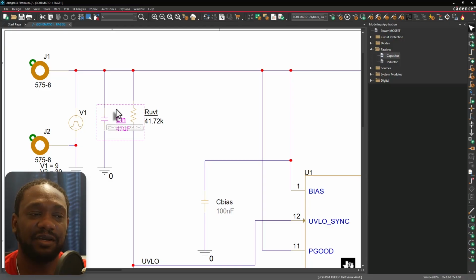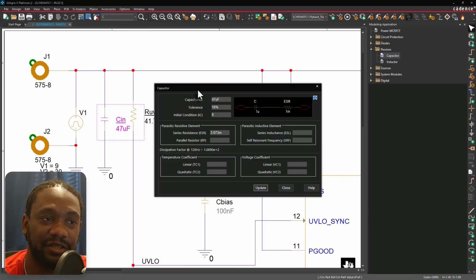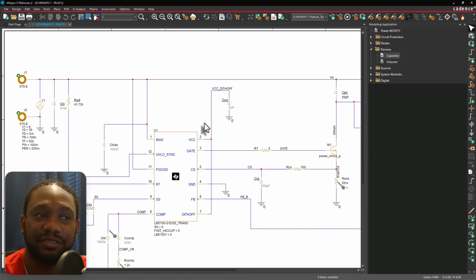Next, I have a non-ideal capacitor. Using non-ideal components that have real initial conditions for voltage, real tolerances, equivalent series resistance, just like any real capacitor would, those really help the solver for your circuit simulate more easily, less stress, and not as stiff matrices for your solutions.